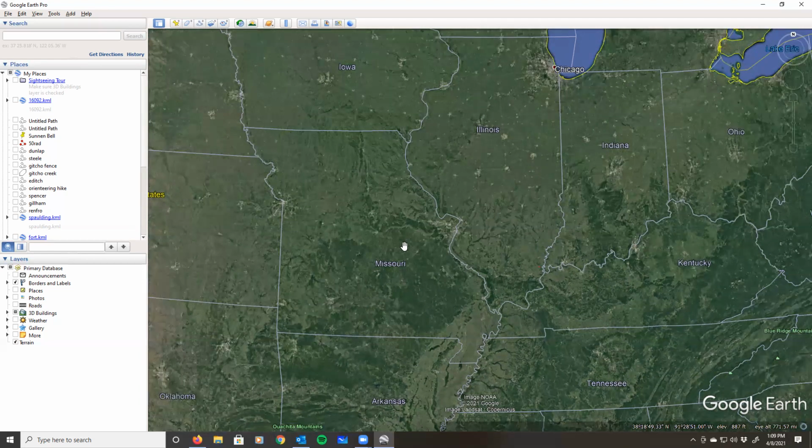So that means that the scale factor at that point is basically 16,999 divided by 17,000. So the scale factor is 0.9999412 on the central meridian.